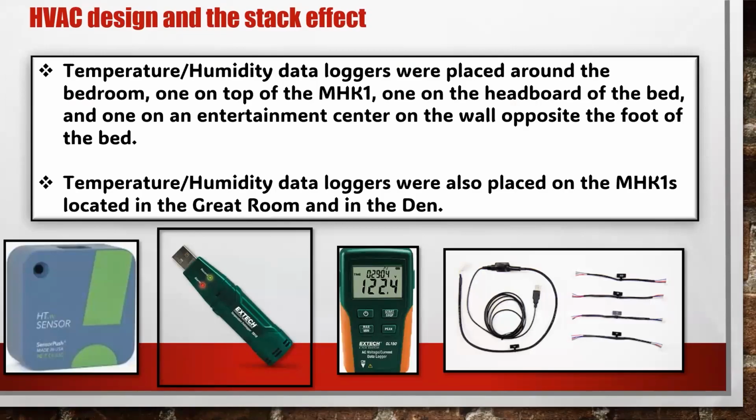Well, the more points you get, the more accurate you can be with your analysis. So, especially like the amp data logger I had to put on the S1 wire. The actual wattage of that unit is so low, most amp data loggers are not going to even record it. In order to do that, I had to make a coil loop multiplier to multiply that amp reading. And because the difference between speeds is so minuscule in wattage, you need to do that or you can't tell the difference between low speed and extra low speed.